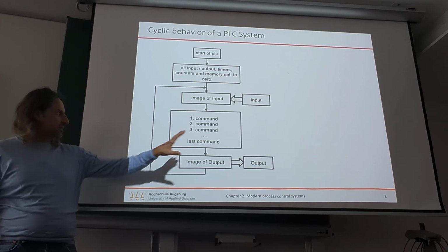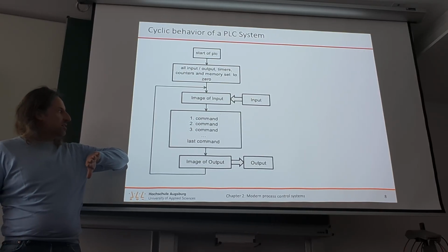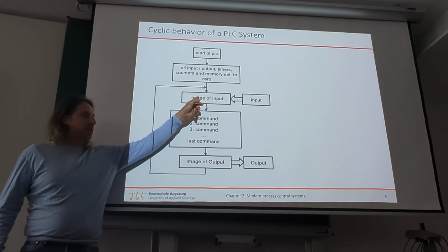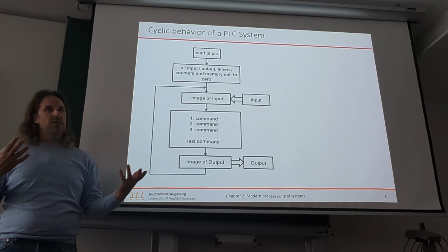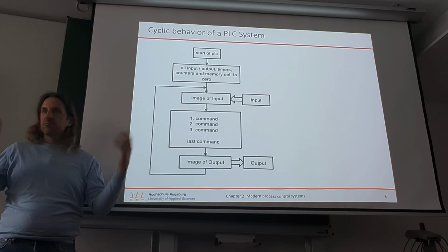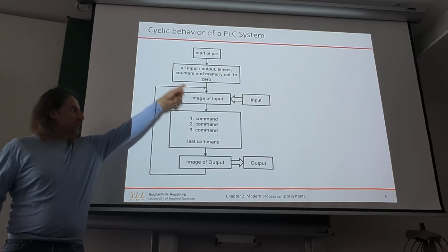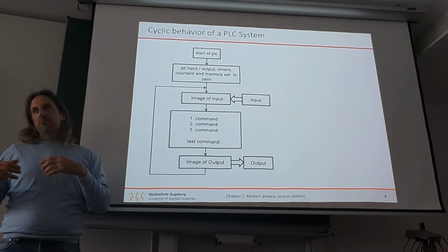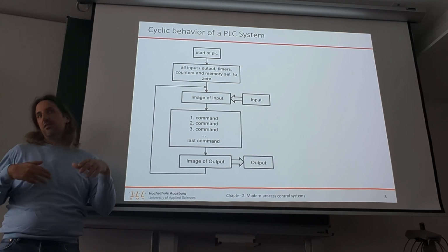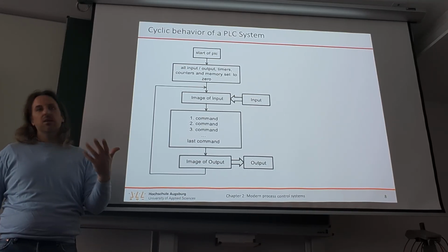But this here is the real-time cycle in the PLC, and basically at the end you start at the beginning again automatically by yourself. So when you program in C, you have this main function, and inside that main function there would be a while loop, that is this while loop, and then I will tell you first read the inputs, at the end write the outputs, and in between write code that is non-blocking, not blocking the while loop. That would be the scenario when it comes to embedded systems to have a similar